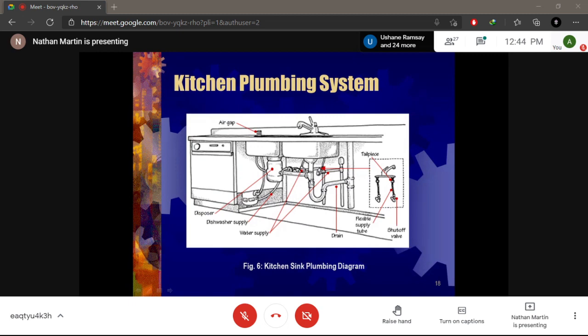So there's no pressure in the drain system, so you don't need any PVC cement, or other persons know it as Tangit. Tangit is just a brand, guys. Please do not write it on any assessment if I ask you about it, right?